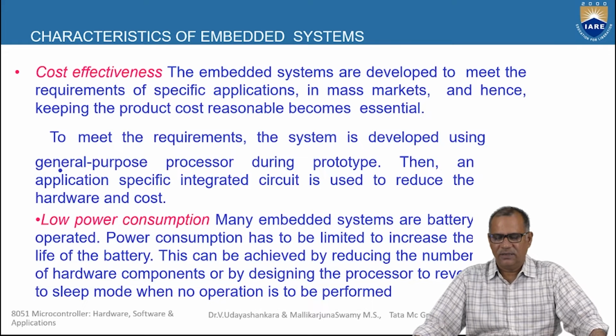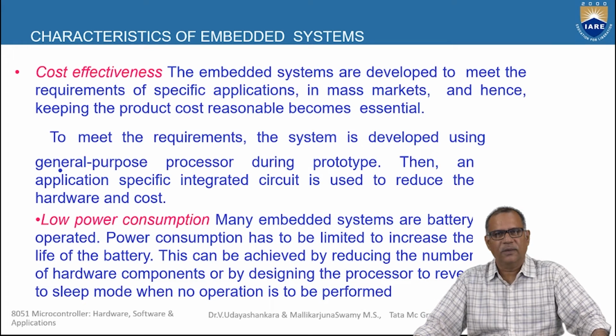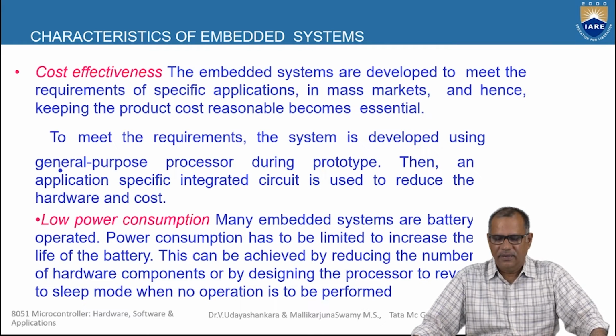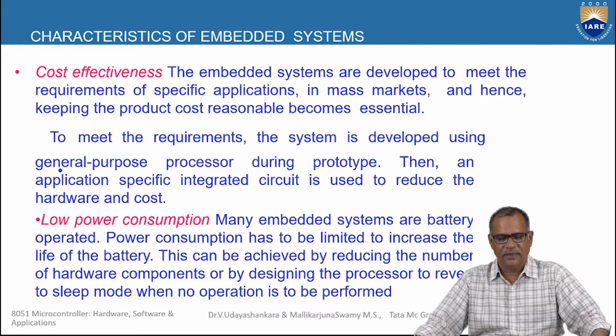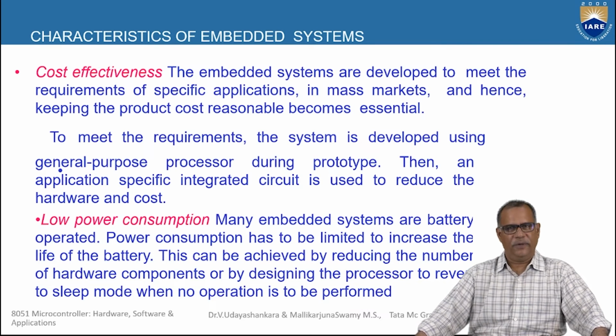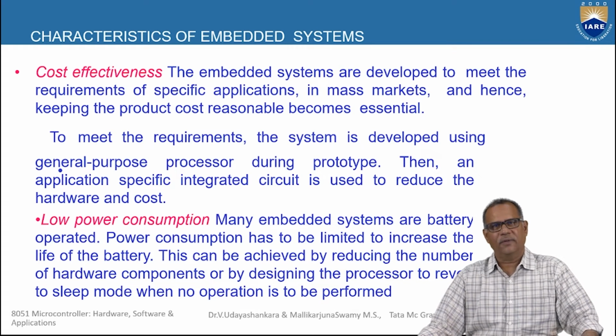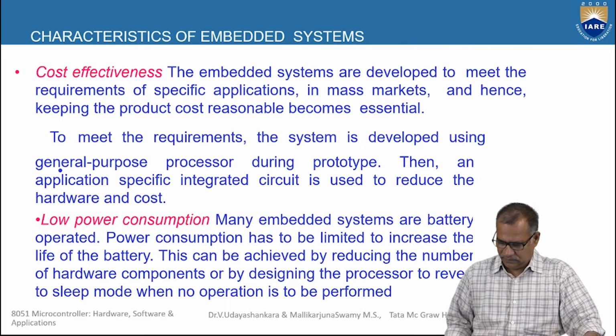So as most embedded systems are battery operated, the power consumption has to be kept less to increase the battery life. This can be achieved by reducing the number of hardware components and by designing the processor to go to sleep mode when there is no operation. In sleep mode, the power consumption is less.